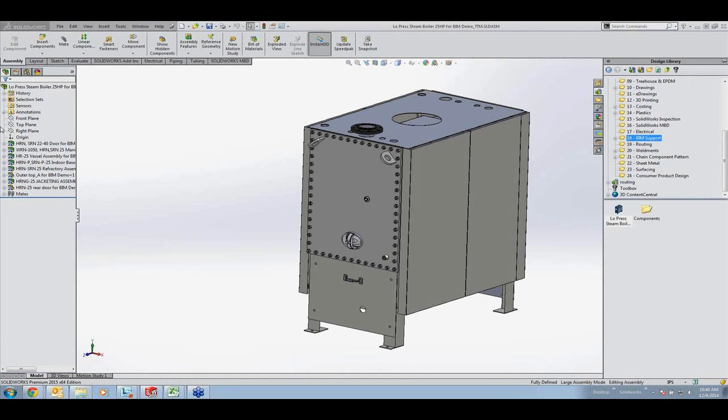We've also created some additional power for the design interface of solid parts here. So see, I have a fillet here. In the past, we've created functionality for conic fillets, but now we have this ability to create an asymmetric fillet. So the radius on one face here is going to be 5 millimeters. The radius on the other face is going to be 10 millimeters. Let me reverse that here. Very easily change the shape of my fillet.